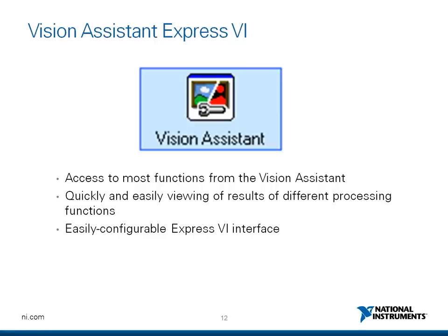Next we have the Vision Assistant. Basically there are two ways of opening or using the Vision Assistant. One, we can use it from the LabVIEW environment, or the other, we can just start the Vision Assistant as a tool from the start menu. The Vision Assistant gives access to most functions, quick and easy viewing of results of different processing functions, and an easily configurable ExpressVI interface.